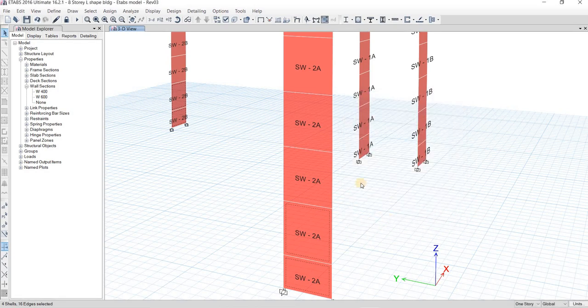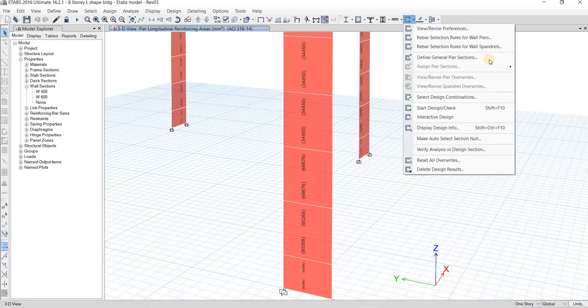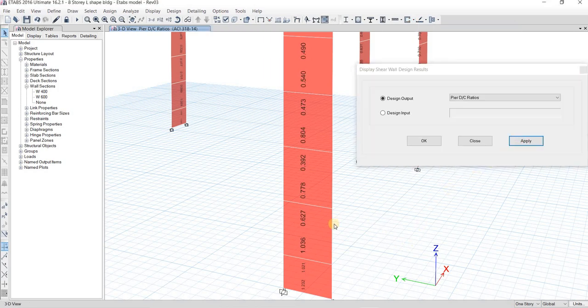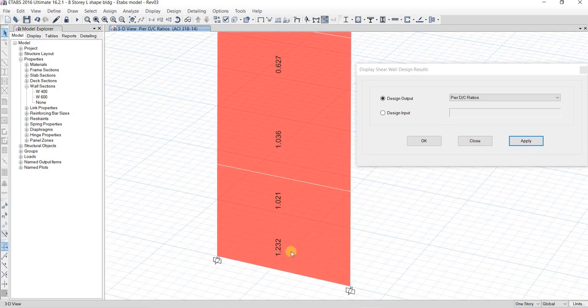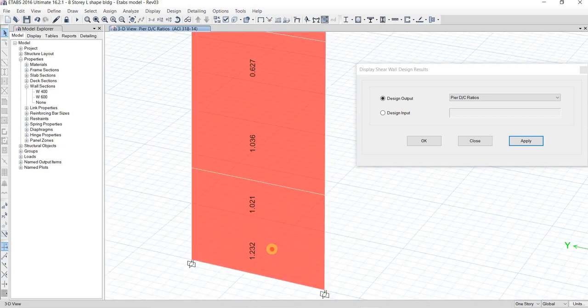You can do it. Or one thing, you can increase the thickness of the wall or increase the rebar. So this is the procedure, but you have to get the value of the building ratio less than 1.